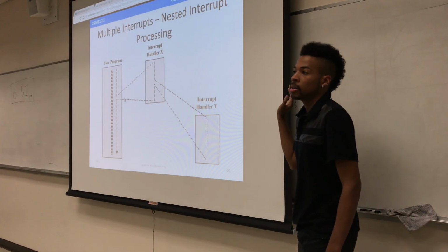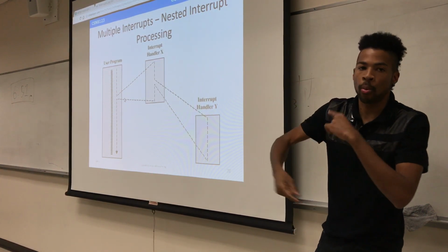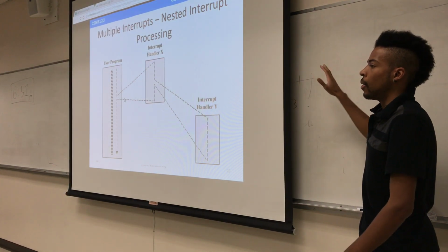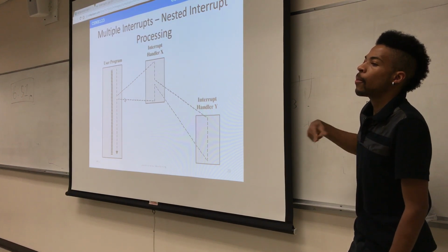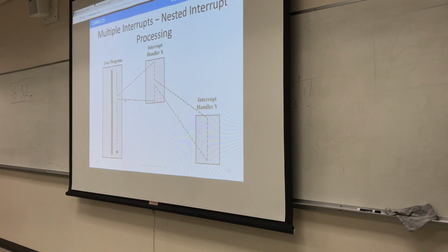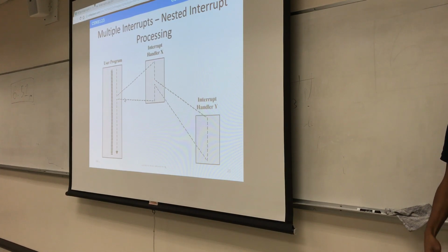And this will keep going on and on. One of the issues is that if you keep getting more and more interrupts, and they're all unique, you keep spawning further and further out, and the higher priority ones get starved when they actually need to happen. The only one in this case that would not be starved is NMI, because it's usually a separate system, usually one pin specifically meant for when an NMI happens. There's usually no vector, no number associated with NMI. It's just: this is NMI, run this service routine. You might be able to gather some information, but you usually want to make those as quick as possible.